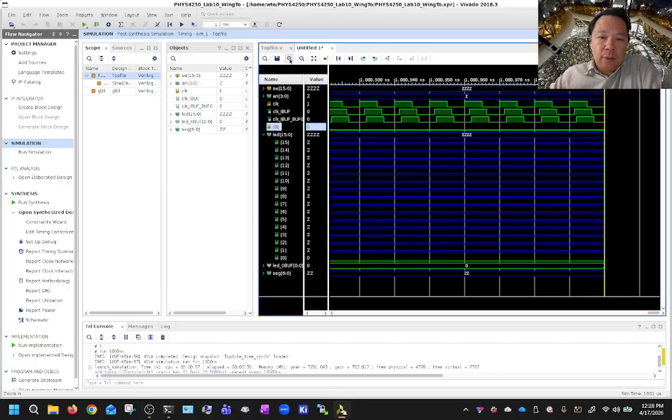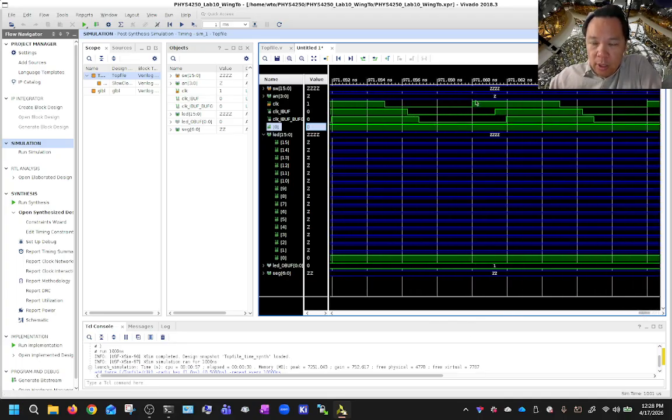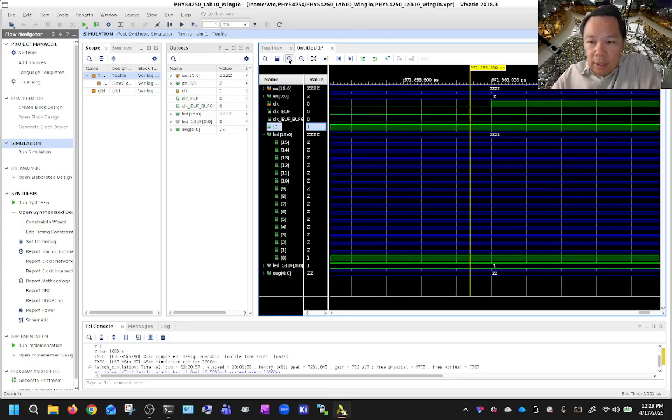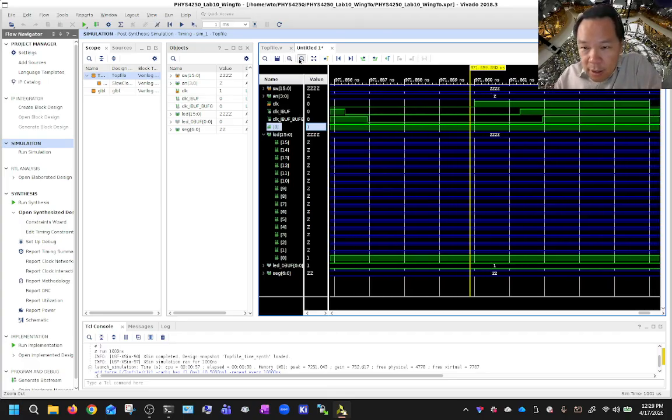Since these signals are so fast, what the simulation is doing is simulating a delay between the clock itself and the buffer. So these buff means buffer. These are the buffers that are interconnected. The real clock happens at some speed, but when you actually receive the signal, there's a slight delay already. You can actually see this if I zoom in even more.